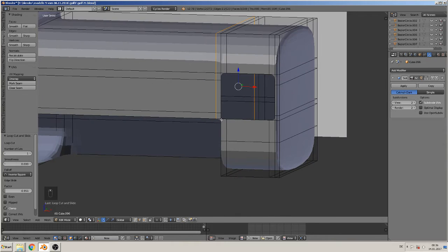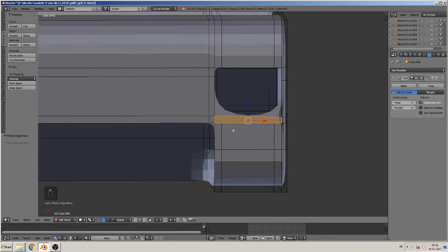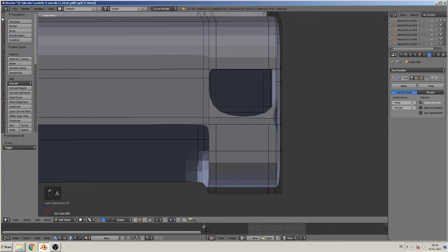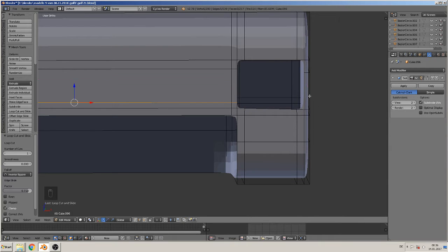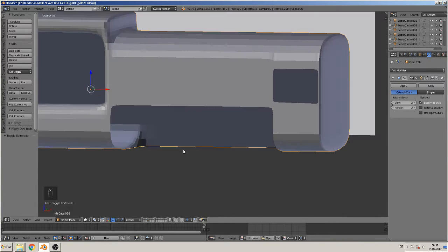We see we have here a problem, there is a hole in there that isn't what we want, so we close that now, F, and now we must cut in here because there isn't something cut. That means we cut through that with the knife tool and cut in here, and you see it will be sharpened up. The same we make with this one here. Good. Now we want to sharpen that up, so we must make here a loop to control that, and here on the side the same. So we have that and this great hole here.